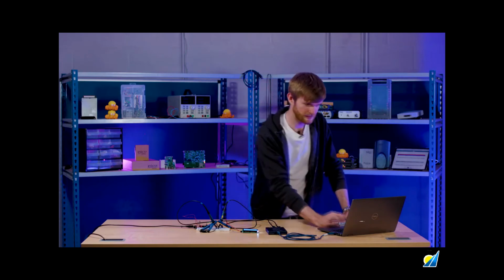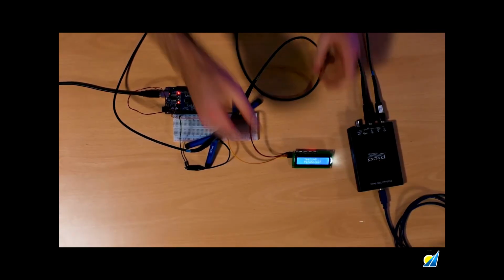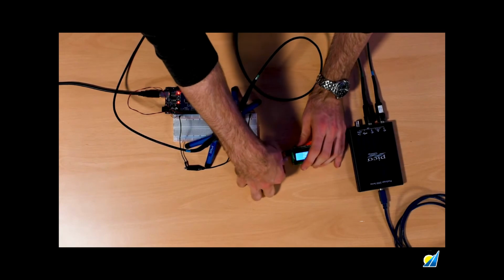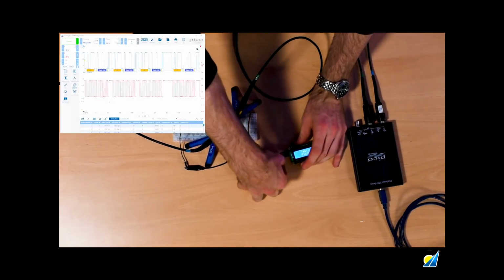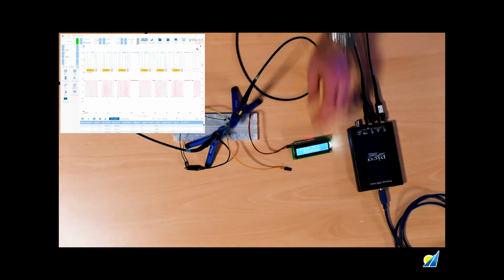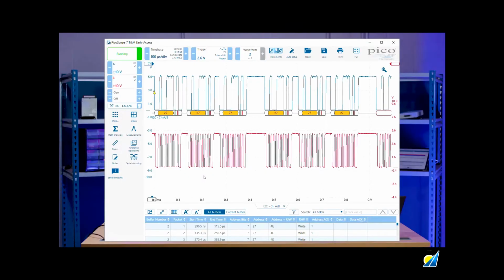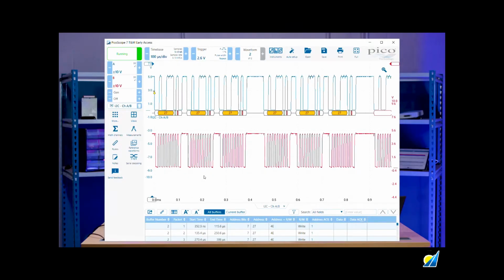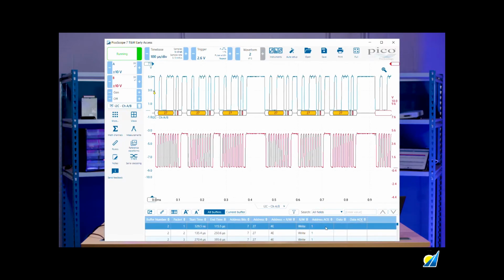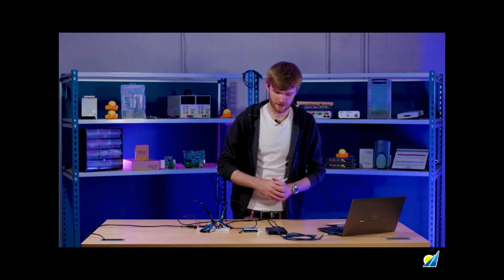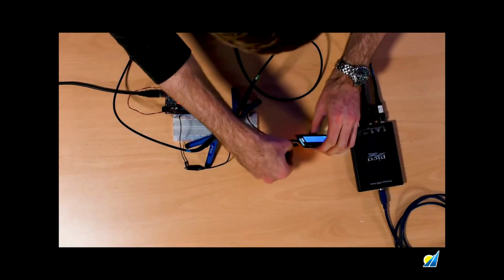And then just like we see here, it's flashing between please, hold, and testing, showing that our data is in fact correct. Right, so now I'm going to disconnect our LCD screen, and you should see something different on PicoScope 7, showing that there's no acknowledgement from the LCD. So as you can see right here, we're getting a 1 from the I2C acknowledgement, meaning that there's nothing coming back from the I2C peripheral you have attached to the Arduino controller. And it's just redoing that per each byte of the information, and it's not getting anything back. So if we connect that back up, then we should start to see data again.